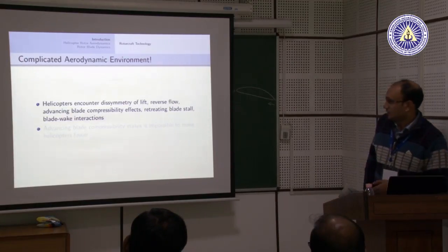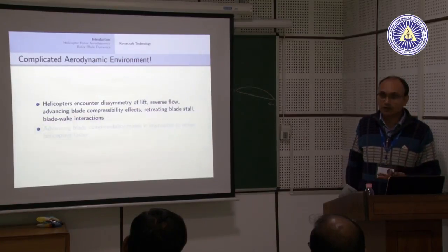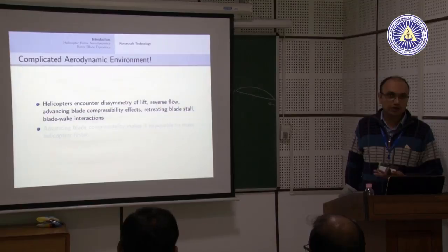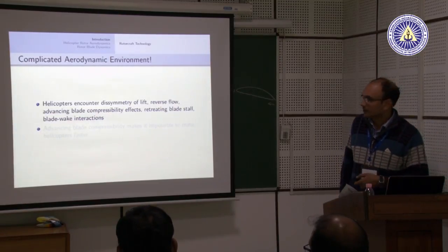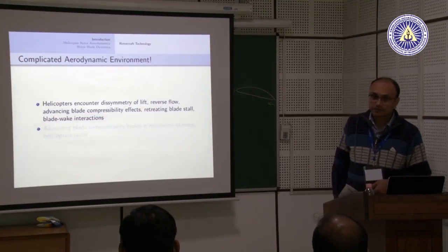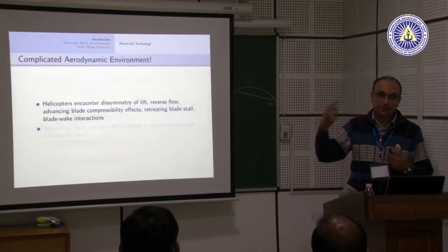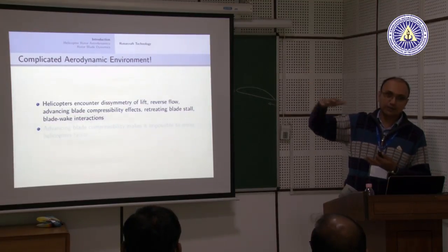But if you see a big Boeing 747, the top speed for that is almost 800 to 900 km/h. That is much higher compared to any helicopter, and the reason for that is this compressibility effect, because my blade is already spinning with a speed which gives a Mach number of about 0.65. That is, the speed of the blade divided by the speed of sound.